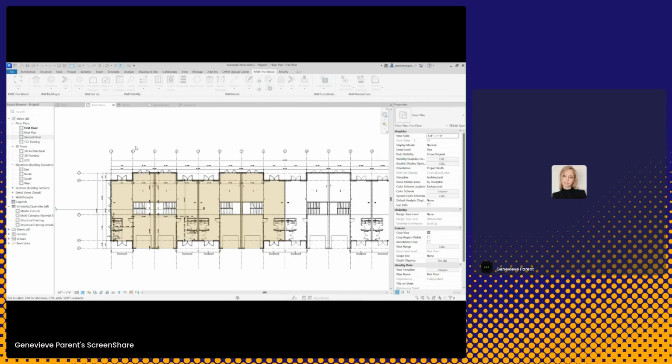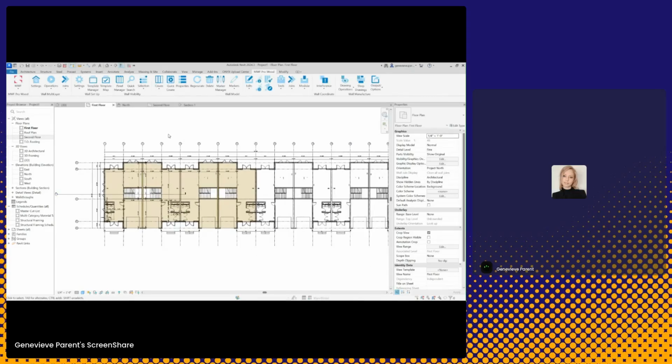We have a template map for level 1, which has all of the walls we would be using in our project and all of the structural templates assigned to them. And we have a template map for level 2, same walls, different templates for the structural configurations. Whichever one you apply in the view you're using is the one that will be read. So I will be applying the one for level 1.